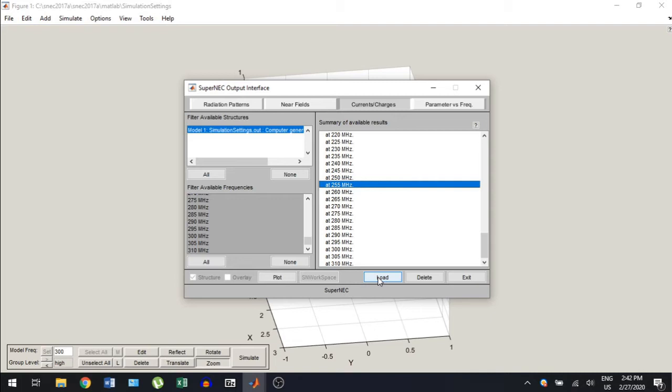If you have selected only one set of data, for example only your electric near fields, it will appear in your MATLAB workspace as a normal data set. But if you selected multiple sets of data, for example your electric and magnetic near fields, you're going to have to once again name it, and it will be set as a structure, or struct, in your MATLAB code, and you'll have to access the elements as they were named individually.